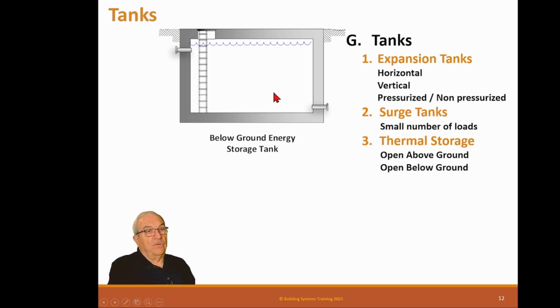And for thermal storage, besides the complex problem of the pressure, the rest is easy, because it's got a fairly good stratification of temperature in the tank. We know exactly how to do it. Ice is much more difficult. This water was pretty simple, and that's why this university has 1.5 million gallons. And they use it to shave off the peak load in the afternoon for their energy savings.